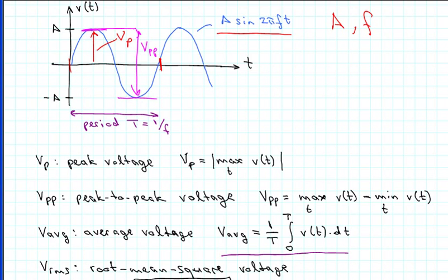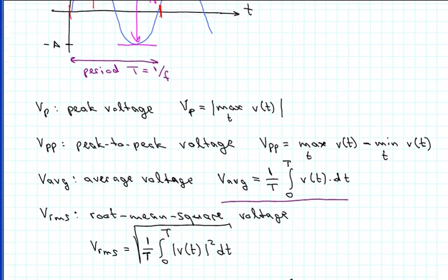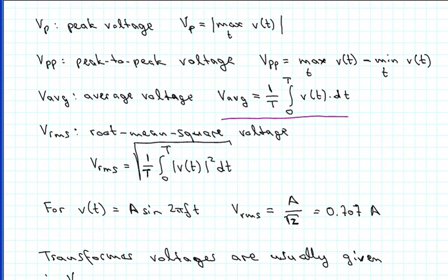And then we could also ask what happens if you take a sinusoidal voltage like that and apply it to a resistor, and how much power that would deliver to the resistor, or to ask it differently, how hot the resistor would be getting from applying such a sinusoidal voltage. In this case, we need to look at something that's proportional to the voltage squared. So that's this quantity here, magnitude squared of the voltage, and then we integrate over one period again and divide by the length of the period.